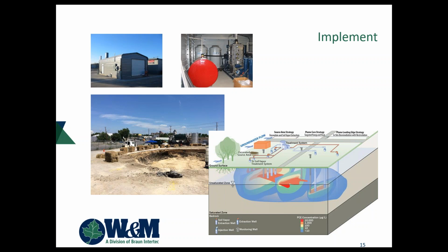So if the zero valent iron doesn't fully reductively dechlorinate your COCs through the abiotic pathway, then if you don't have that bacteria, you'll stall at the daughter products or vinyl chloride. So you've got to go back and add the Dehalococcoides bacteria after the geochemistry of the site gets where it needs to be for those bacteria to be happy.